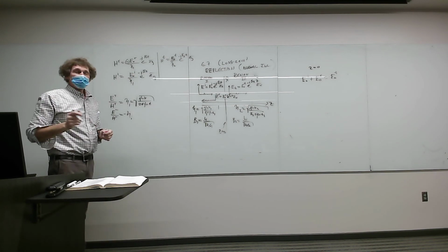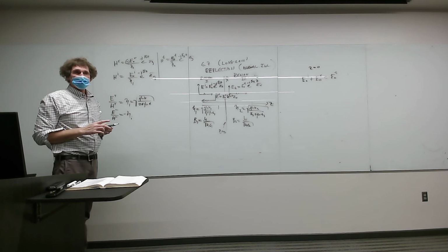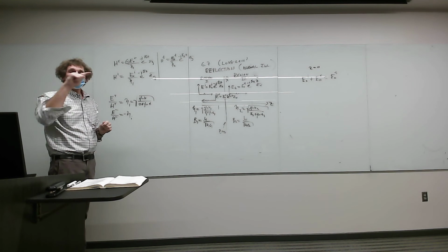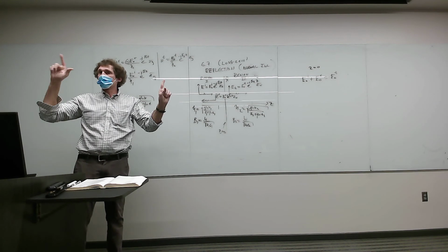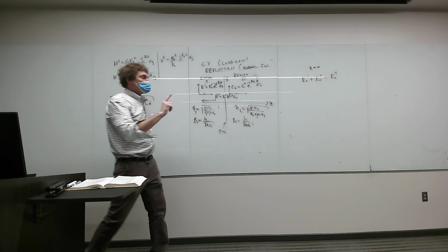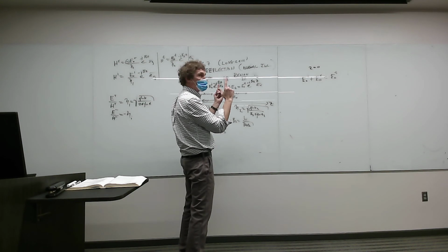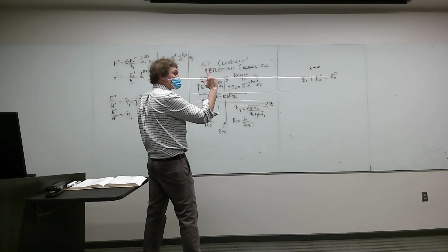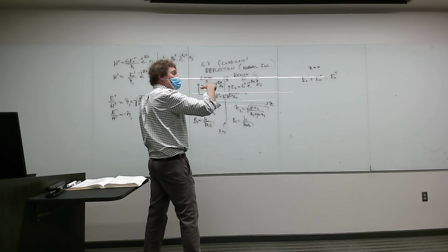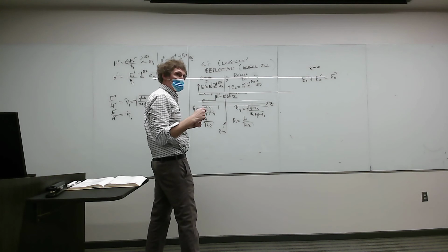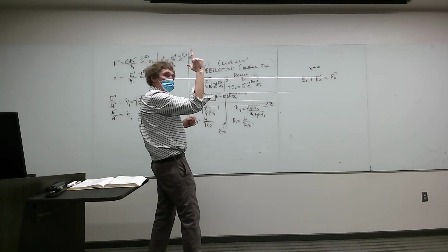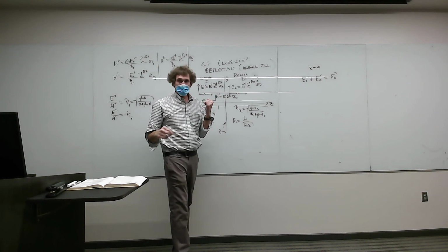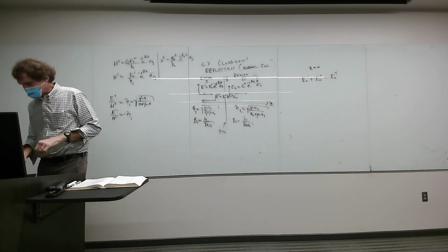So, another reason this is a minus, I'll just tell you this. Take a breath. Remember how whenever you have E crossed H, it's the direction of propagation. Do y'all remember that? So if this is the x-axis that way, and you're going in the negative z direction, well, E crossed H means the H field would have to have a negative a y sense. Do you all see that? It would be E vertical crossed into H would be that way, negative. You good with that, everyone? So that would be the case.